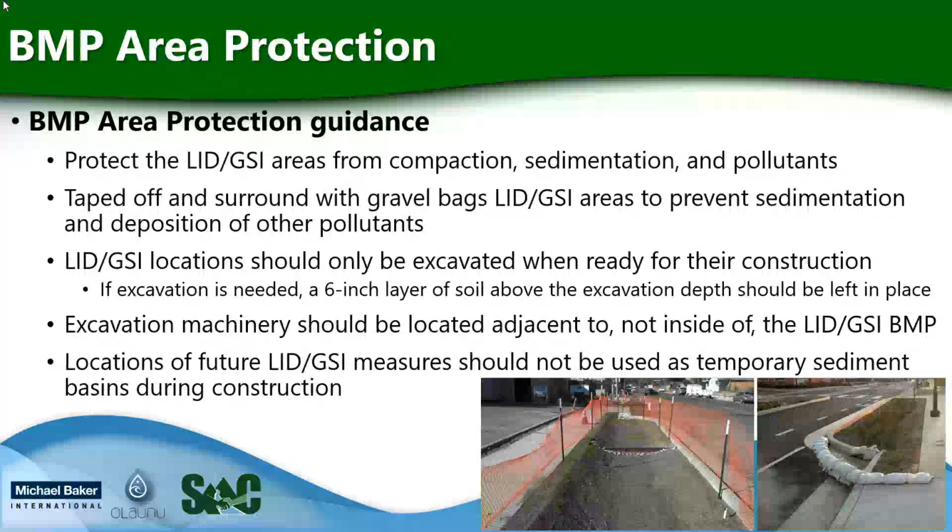Construction stormwater flows may carry fine sediment into the LID GSI area, which may reduce or eliminate the ability of these locations to infiltrate stormwater, which would negatively affect the overall LID approach for the site. Additionally, the weight of the water may result in compaction of the area, including the substrate, which would reduce or eliminate the infiltration capacity of the future LID and GSI system.